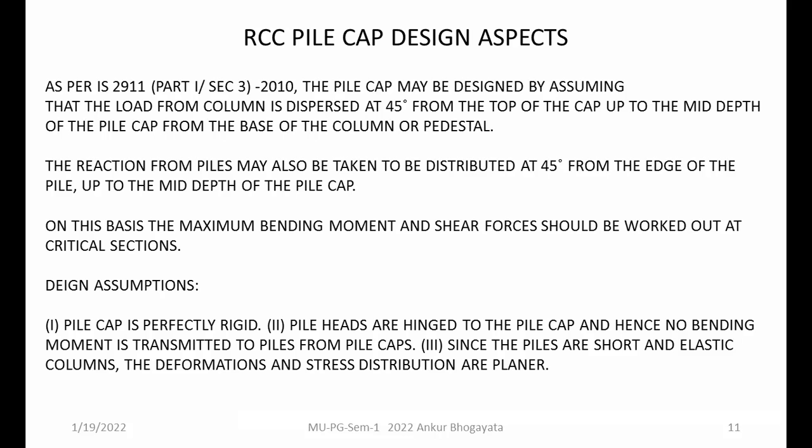So none of the sections will suffer from the lack of reinforcement. So by default, the flexural part is taken care of by the pile cap. So ideally, it is assumed like this. Especially the second assumption becomes very important when you are designing the pile itself, which right now is not the case.